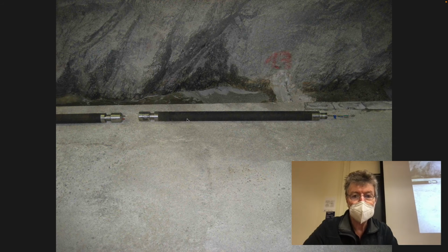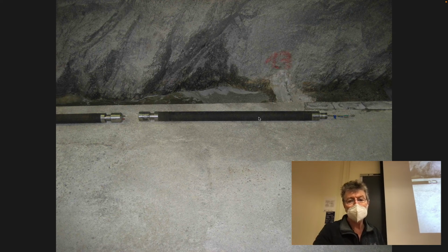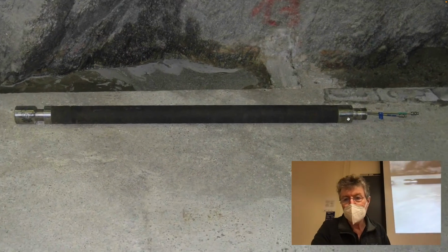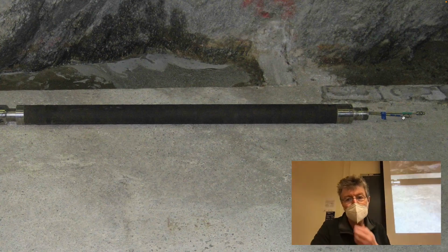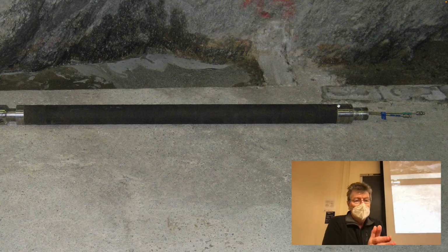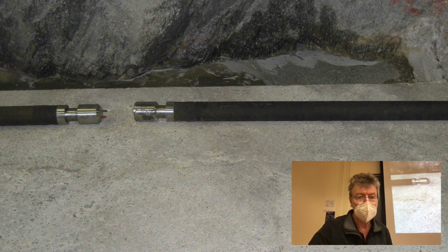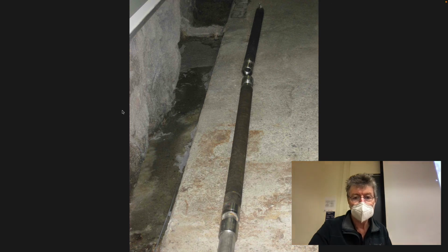So here is an aluminum mandrel with a neoprene sleeve on it. If you look at one end, you can see that there are supply lines to supply pressure to inflate this balloon on top of the mandrel. Put it down the borehole, inflate it against the walls. You have two of them so that you have a zone between them. The lower packer is linked by a gas line to the upper one, and you're able to inject fluid along the boundary between them.